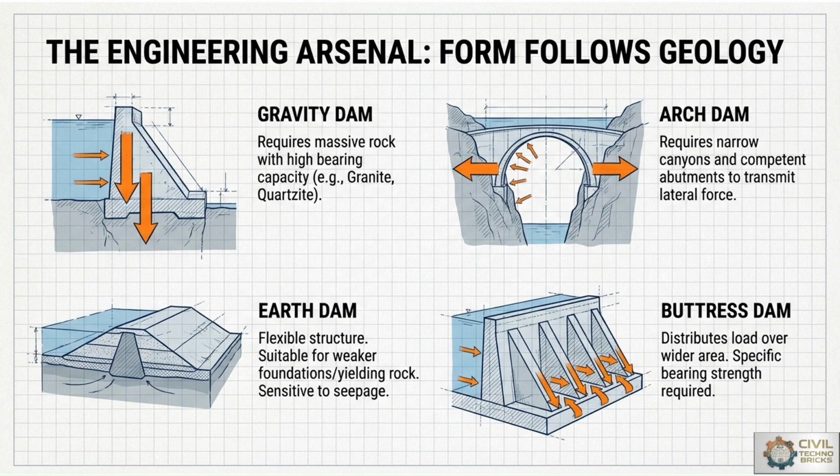classification is based on these four parts. So different dam types are selected based on geological and topographical conditions of the surface. Gravity dams require hard, massive, and impermeable rock foundations to resist heavy loads.